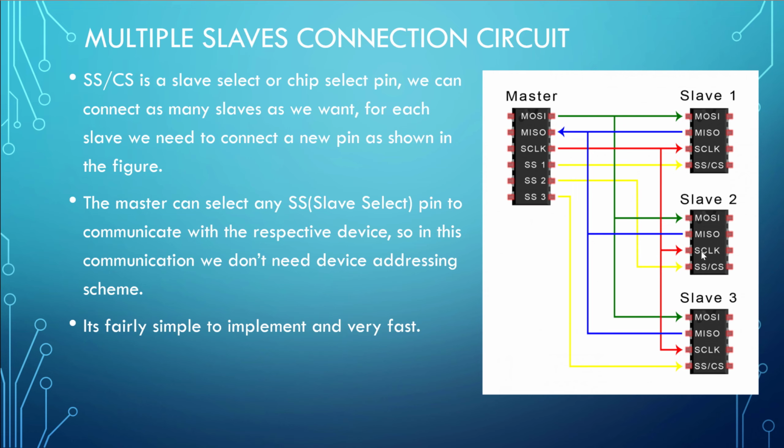If you have transmitted some data, you won't get an acknowledgement signal back like you have seen in I2C communication. But it's very simple to implement and very fast, so it's mostly used with flash devices, high-speed accelerometers and some advanced devices which need a lot of speed.